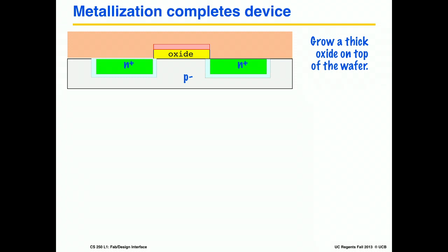Right? There's other materials like gallium arsenide, for instance. When it oxidizes, the oxide is like a powder. It's not stable, so it's hard to build these kind of 3D structures. It's a nice property about silicon, and one reason why it's so popular. Oxide is hard. Silicon dioxide is almost like glass, and it's very close to glass.